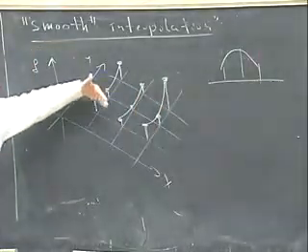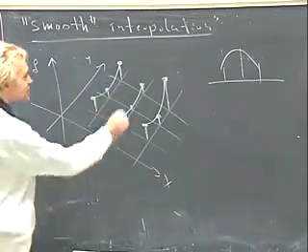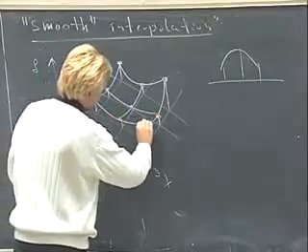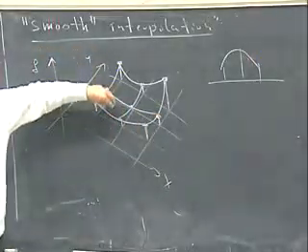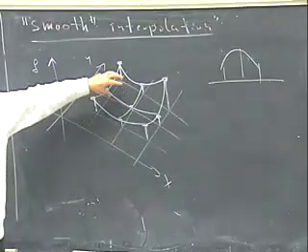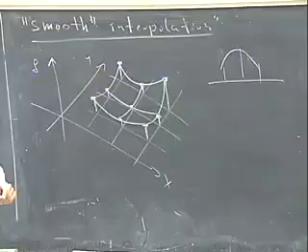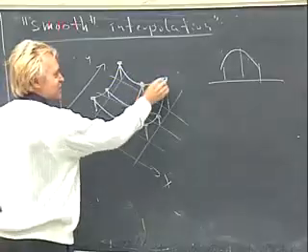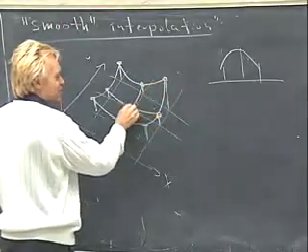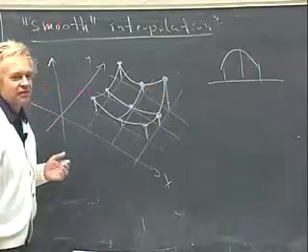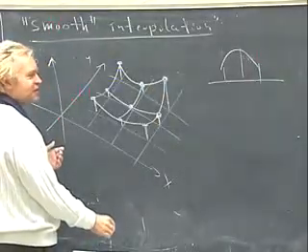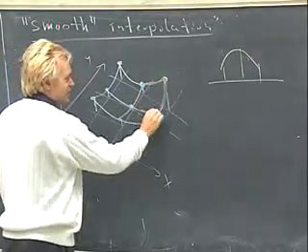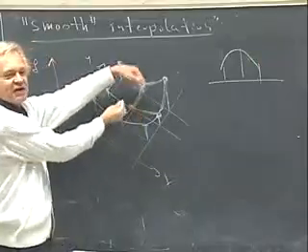And now I can also do it in the x direction, 3 times the curve scheme. That's a cool surface already, right? But still, there's nothing in there. It's empty. I have to worry about the representation for the stuff in between 4 curves for each quadrilateral. So now you have changed the problem from 4 neighboring points to be interpolated to the problem of having 4 boundary curves that need to be interpolated in between.